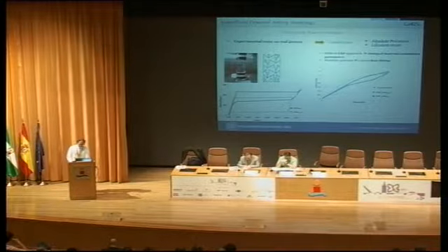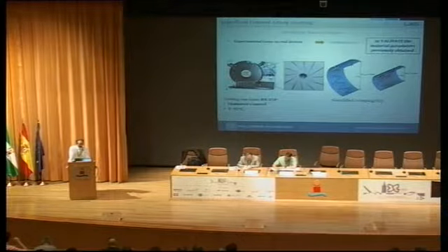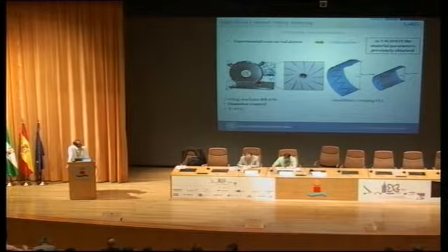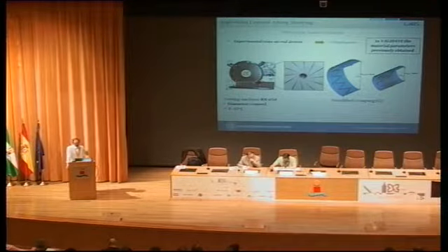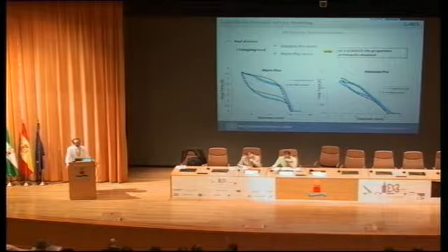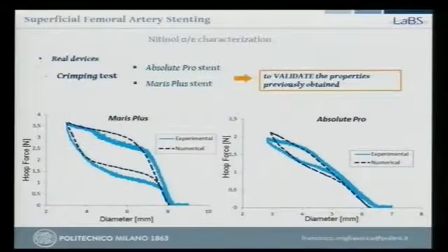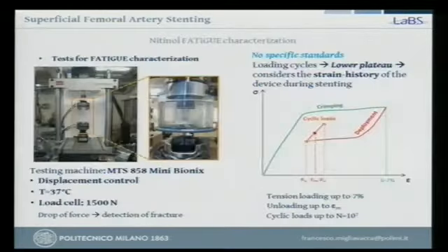Is this true? So let's do another validation. So let's do another experiment. We took the stents, we did a crimping experiment, and we measured the force to crimp the stent, and we ran in parallel an in silico simulation with the constitutive law that we identified previously. And these are the results. So for two different stents, of course they are not completely superimposed, but the results are quite satisfactory, keeping in mind that we have run a model. So this is a way to identify the mechanical properties of the stents and the nitinol. That was just static simulation or static test.